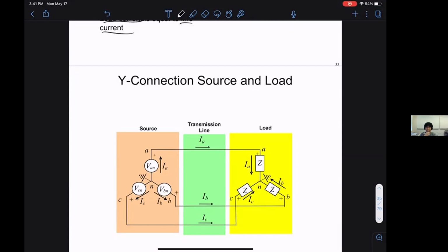This load balancing often happens at a substation or at a distribution system feeder head. Each home may not be all that balanced. But when we design the distribution system, we want to make sure each phase has roughly the same number of houses, or roughly the same amount of load on it. Then in real time, we may do some switching to make sure these loads are balanced.